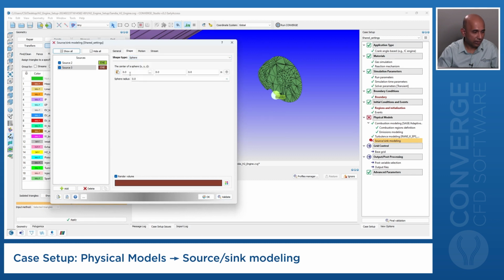location, a sphere at 0.0419461, and here it's 3 zeros, 61, 0695, and 2 zeros, 173, 196. Again, where do these coordinates come from? Your spark plug location. Okay, the sphere radius should be 0.5 millimeters.